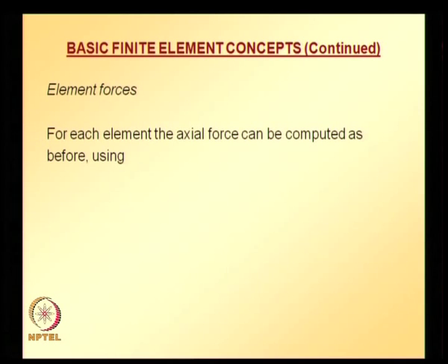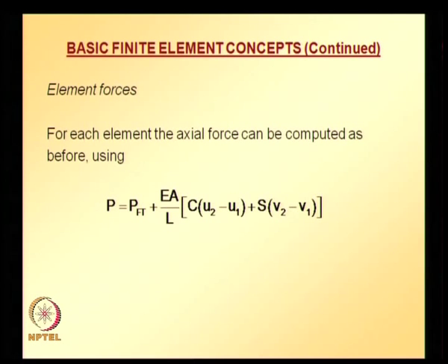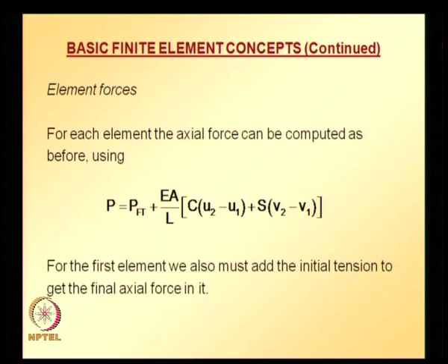For each element, axial force can be computed as before using this one. Only the first term is additional, which is the contribution from lack of fit. For element 1, we have this term; for element 2 and element 3 we do not have this term. So, for the first element we must add initial tension to get the final axial force in it.